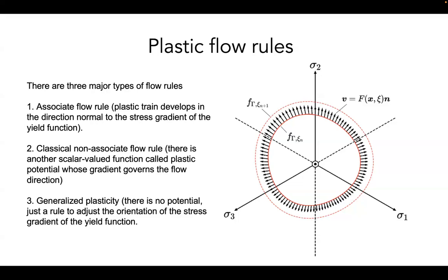Because then I need to come up with a Drucker-Prager cone as my plastic potential, but the advantage is that when I shear the material, I can get some dilation. Okay, this is actually a trick. But the problem is that I have to write the plastic potential, so this also creates more burden for the inverse problem. And as I said before, if you have an associative flow rule for J2, that's fine. If you have a non-associative flow rule, it is just a plastic potential that is also a cone but a little bit bigger, that is fine.